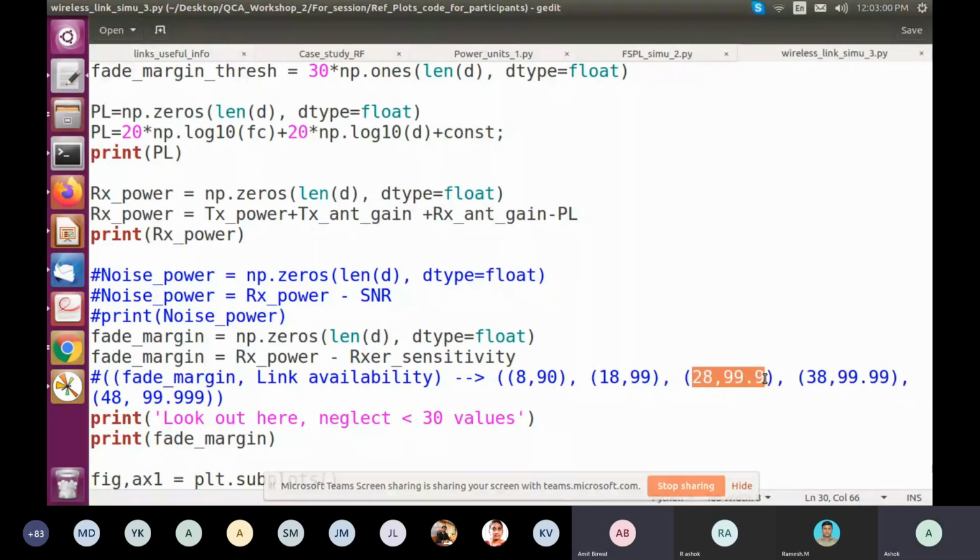You see, typical communications are either LOS or NLOS, line of sight or non-line of sight. So you model the line of sight component using free space path loss and add a fading margin based on your multipath. Because for any signal, even if you work it out for LOS, there would be a tree or some obstacle, even in rural areas, because of which it becomes NLOS. Even in the best of conditions, there will be NLOS sort of reflections. And for that, you model this extra parameter and you come up with it.